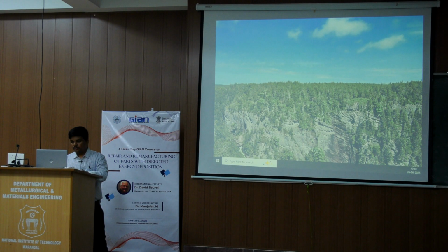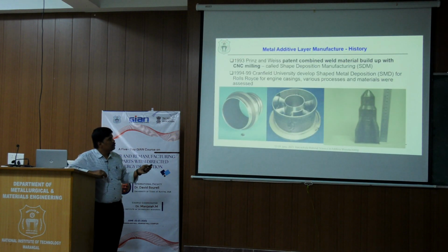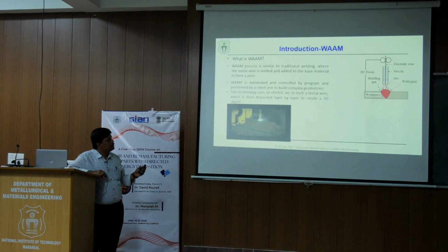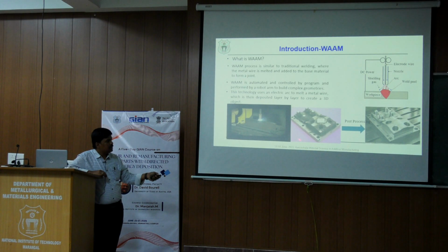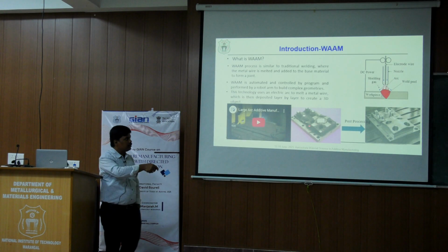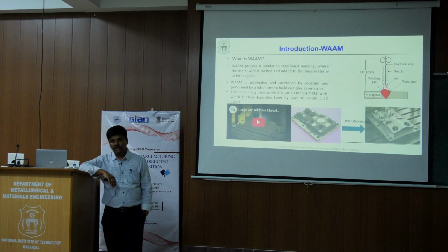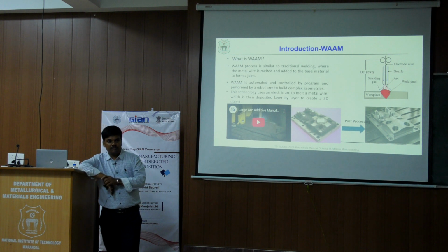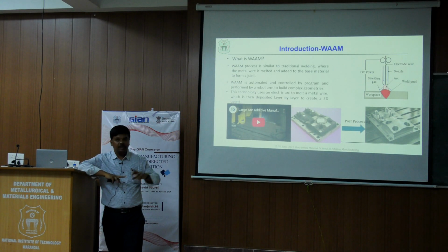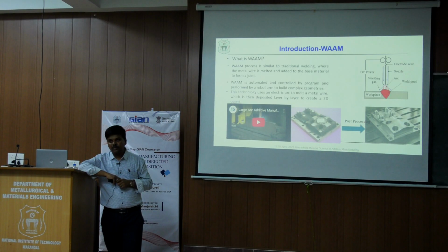With respect to the WAAM process, we have made several studies, and I will go through this quickly. These are some of the big parts made by the WAAM process, and one of the die designs they have made with WAAM. But if you compare this WAAM process with the DED process, which is going to be more beneficial when you want to repair dies: the laser powder DED process, laser wire DED, or maybe arc DED?